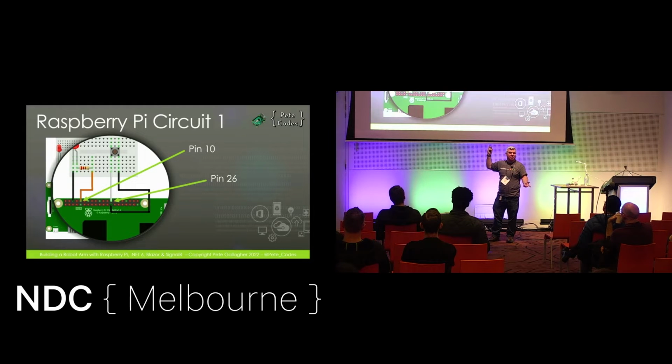So if you're doing this with an Arduino, you'll likely need a resistor pulling that up to a high value. And then when you press the button, you'll see it's connected to ground, and that goes low. In the Pi, we've got internal pull-up resistors, so we could turn them on, and you'll see that in the code. But it does make the code seem a little bit backwards in that when you press the button, it goes low, which is false, and if you don't press it, it's high. So you'll see in the code, it feels like it's a little bit backwards.